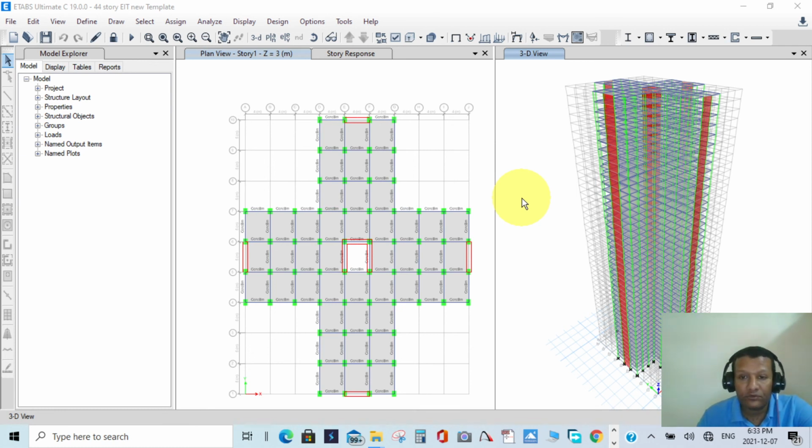But if we use a single degree of freedom system with a constant damping ratio and a fixed time, and we run our system, pick the maximum displacement, and run our system for different time periods, and construct our displacement response spectrum, we derive the pseudo velocity response spectrum and the pseudo acceleration response spectrum from our displacement response spectrum by multiplying by omega for the pseudo velocity response spectrum, and for the pseudo acceleration spectrum we multiply by omega squared. And we can simply find the response spectrum for our site.